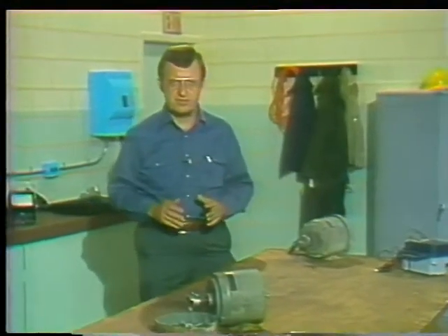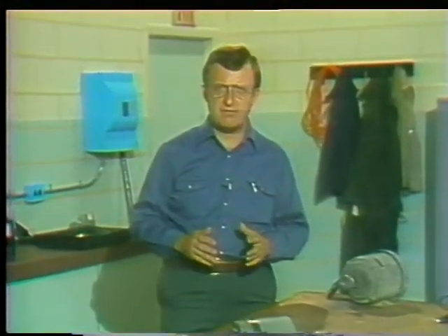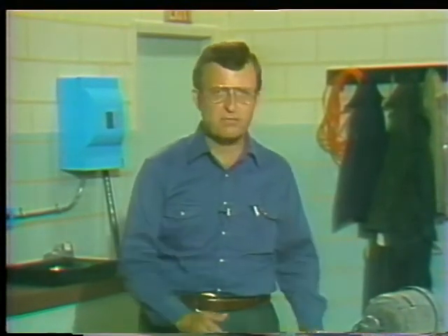The difference between the speed of the stator's magnetic field and the speed of the rotor is called slip. And slip is very important because it determines the amount of power the motor produces. It also affects the amount of voltage induced in the stator. The greater the slip, the greater the effective voltage in the stator.